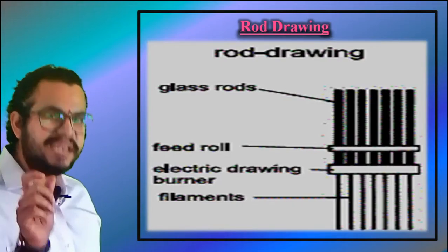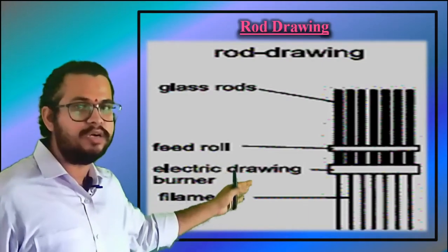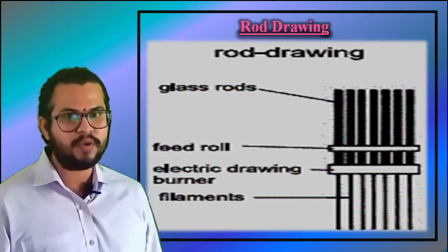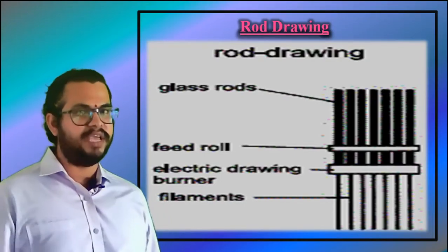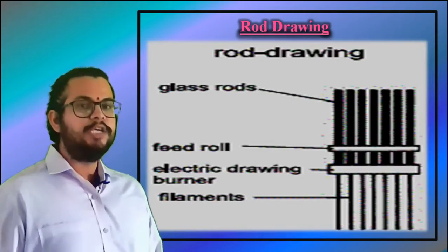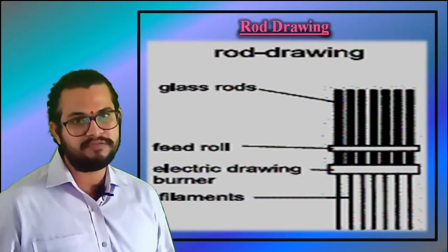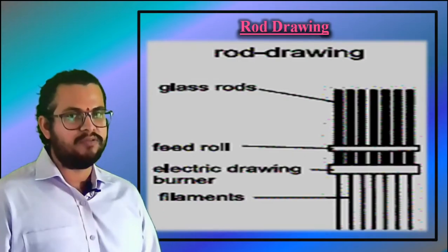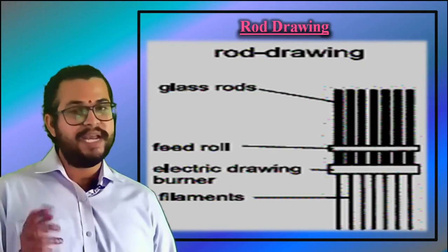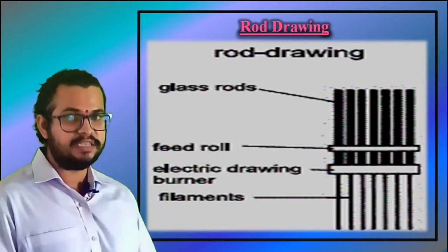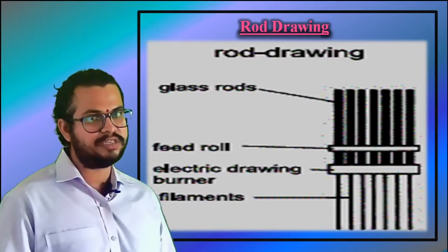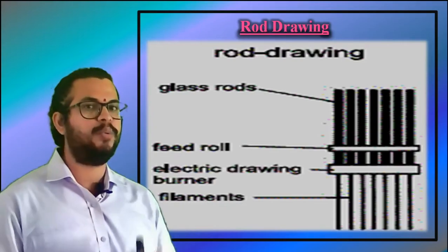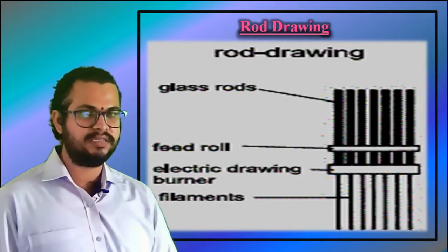Machine performance being limited by the number of glass rods fed in, the rotating drum may sometimes be combined with nozzle drawing, which results in drum drawing. So this multiplies the performance of the machine. The dry web is again laid down onto a perforated belt and solidified, or after winding it, so as to receive slivers cut for further processing on machines producing wet laid non-wovens.